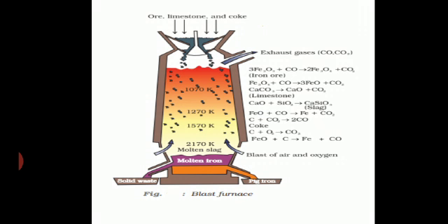The zone just above the zone of combustion is a zone of fusion. In this zone the temperature varies in the range of 1475 to around 1600 Kelvin. The sponge iron coming down from the slag formation zone is being absorbed by carbon, silicon, phosphorus, manganese, etc. It melts in this zone at this particular temperature, that is around 1570 Kelvin.